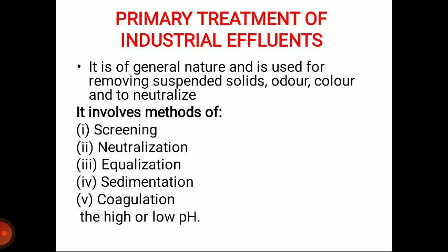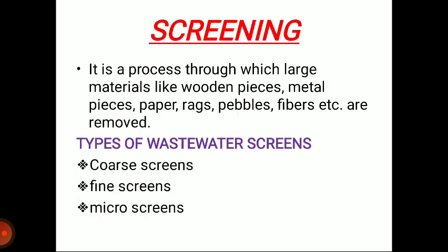Primary treatment of industrial effluents. It is of general nature and is used for removing suspended solids, odor, color, and to neutralize high or low pH. It involves methods of screening, neutralization, equalization, sedimentation, and coagulation. First, we will discuss screening.